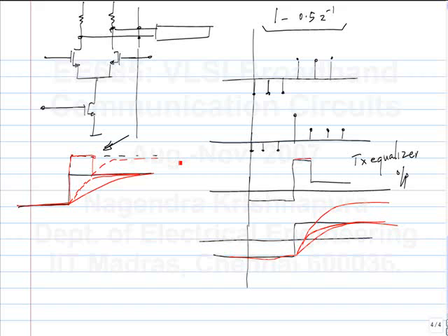Now I don't want this FIR-like approach with different differential pairs with delayed inputs and all of that. I want a more continuous time analog approach of realizing the equalizer. And I also said effectively what I'm doing when I'm equalizing is creating an overshoot. If you have more taps, you will create more complicated responses. If you have a precursor tap, you will have an undershoot. And then if you have more taps, you may do something of this sort.